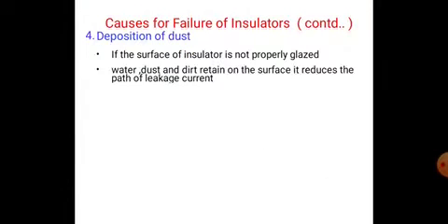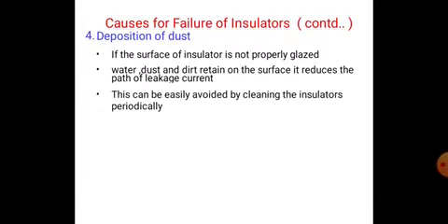Deposition of dust. If the surface of the insulator is not properly glazed, water, dust and dirt retain on the surface. It reduces the path of leakage current. This can be easily avoided by cleaning the insulators periodically.